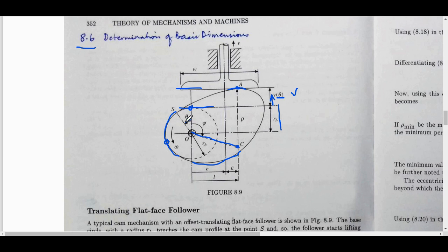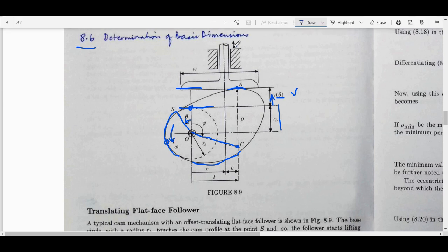What is interesting and what you need to understand is that for up to 2 derivatives, theta plus psi is constant, because this point is fixed in the cam and this line is also fixed in the cam. Okay, the cam rotates as indicated over here. This will move. It moves with a certain velocity. That's fine. Over here is the eccentricity and the offset E, and then there is the eccentricity epsilon, which varies with time. The offset E is fixed for a given cam design.